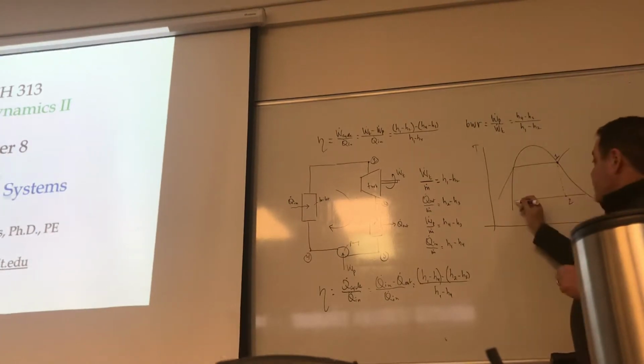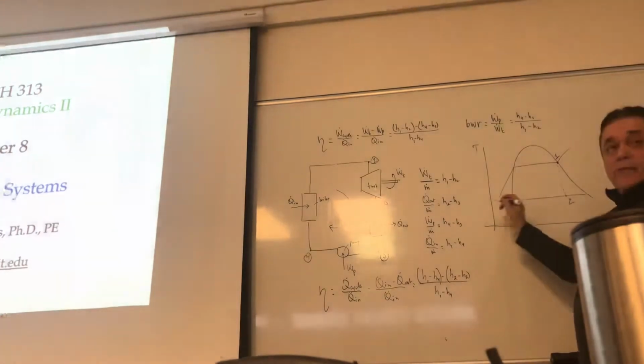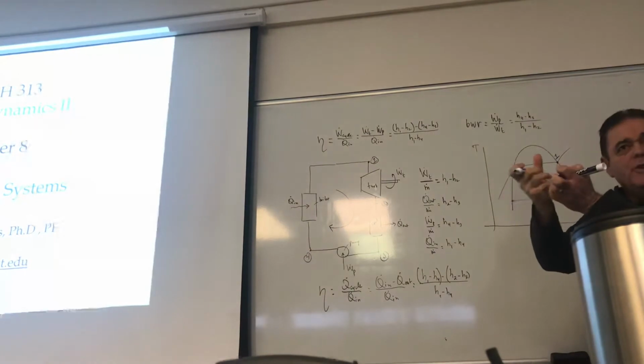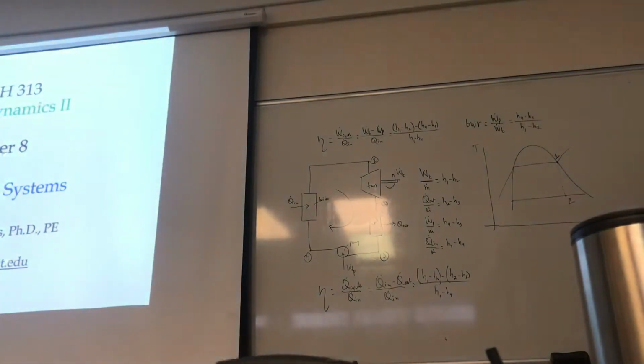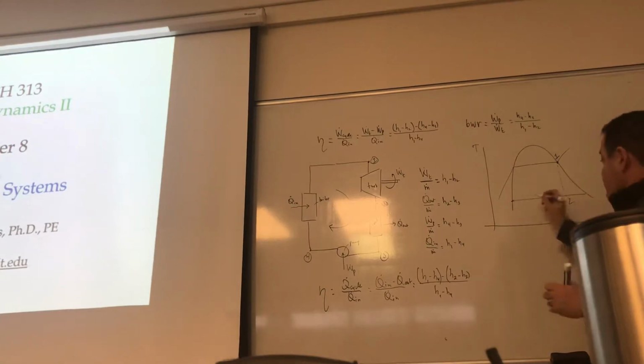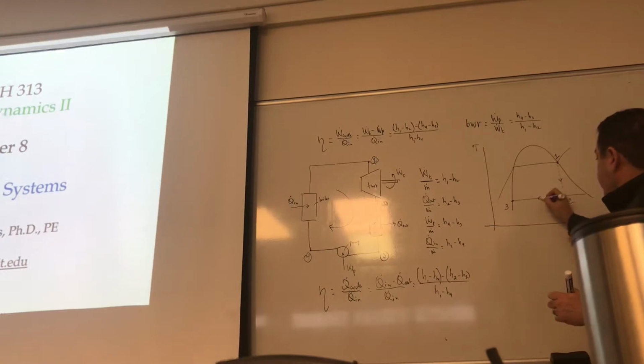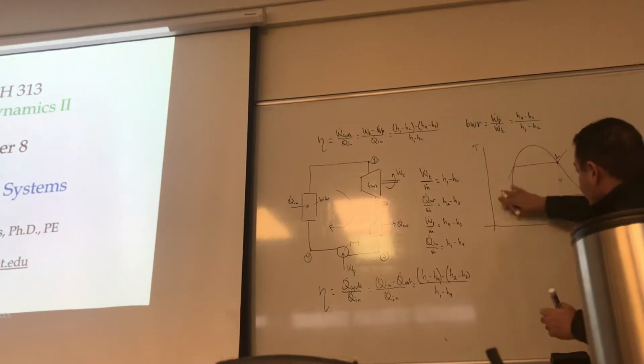Then between 2 and 3, I'm going through the condenser. The condenser, at constant pressure, removes all the extra heat. I want to turn all my vapor to just liquid, so my state number 3 is going to be here.